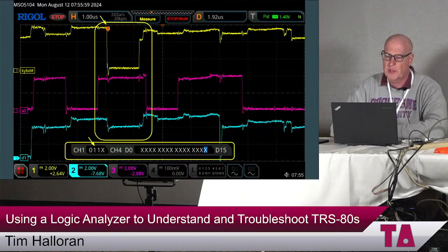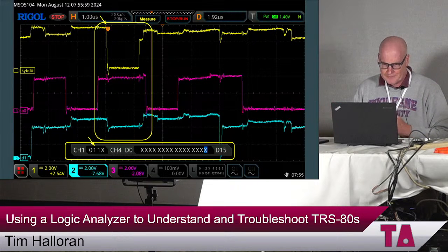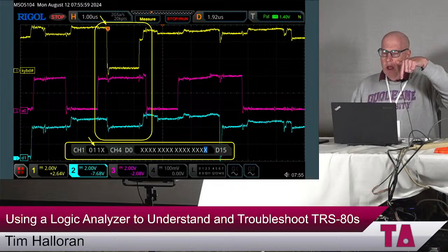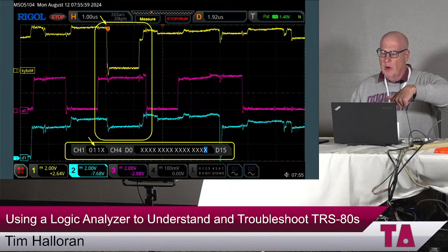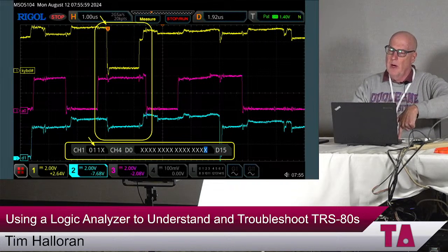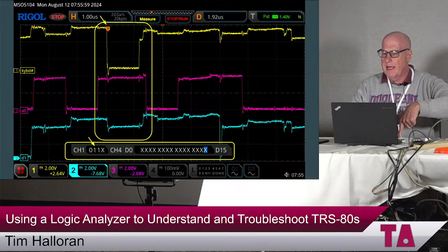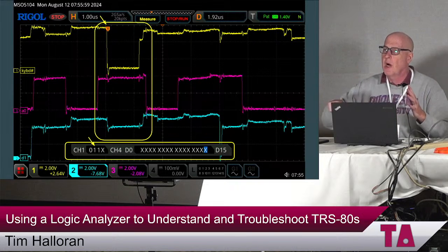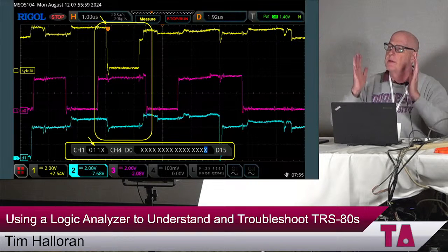All right, so drilling in here, we're able to set that what we want is channel on the first probe to be low. Then we want the A0 line to be high and the D line, the output data line, to be high as well. And in fact, that's what we're seeing. So we're getting something very similar to the logic analyzer. We're not getting that overdraw where most of the time it's low, but some of the time it's high.